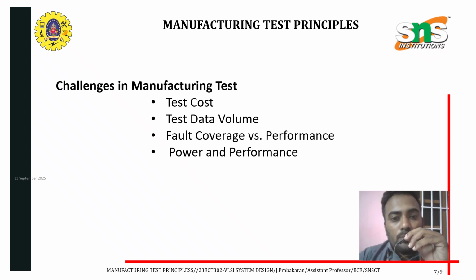Okay, manufacturing test ensures a defect-free, reliable product. It relies on fault models, test pattern generation, and simulation. It involves DFT techniques to simplify test application and reduce cost, and supports yield improvement by providing feedback to fabrication.